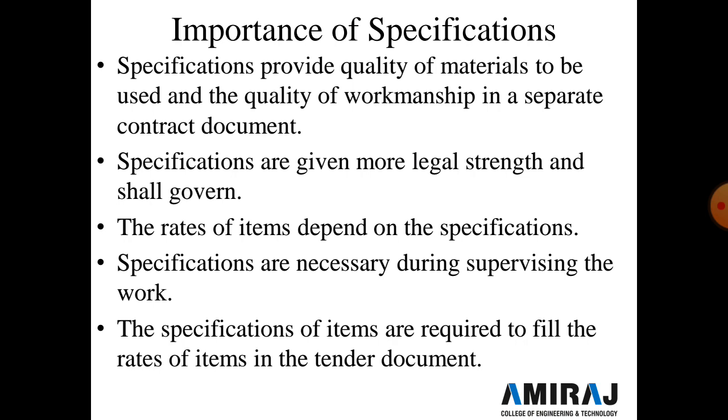In case of a discrepancy between the drawing and the specification, the provisions of the specification are given more legal strength and shall govern, and the rate of an item depends on the specification. If the specification is rigid and demands superior quality, the rate of the item will be increased, and vice versa. Specifications are necessary during supervision of the work. The specification of items is required by the contractor to fill the rates of items during the tender documentation work.